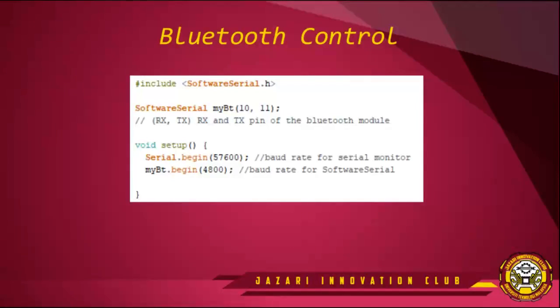So we start the Bluetooth by including a library here. We are using a simple library, SoftwareSerial.h, with capital S, both S are capital. So you need to declare the object, with the data type being the name of the library, SoftwareSerial.